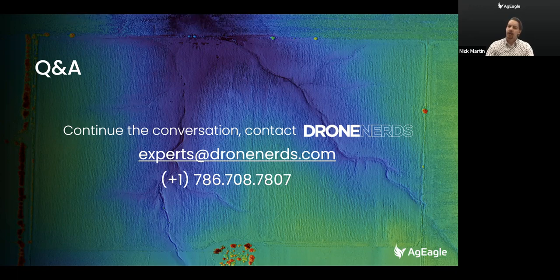Yeah, just like checking out the growth rates of cotton, absolutely. You fly that field once a month, you develop an NDVI or an NDRE map, and you'll absolutely be able to see the changes over time in a cotton field. That would be a really good application for a multispectral sensor, absolutely.